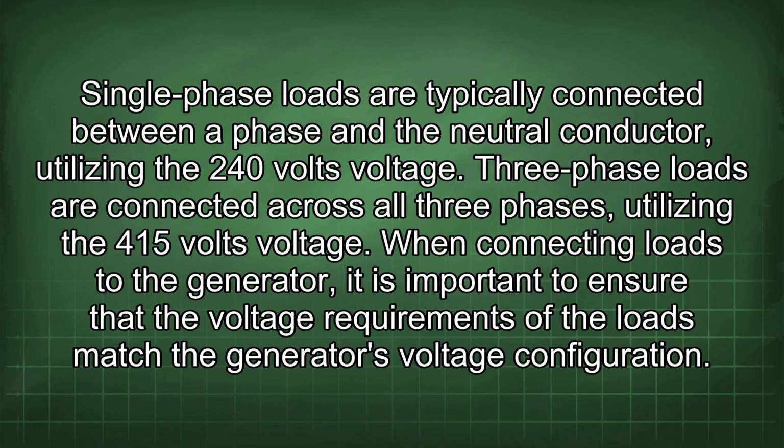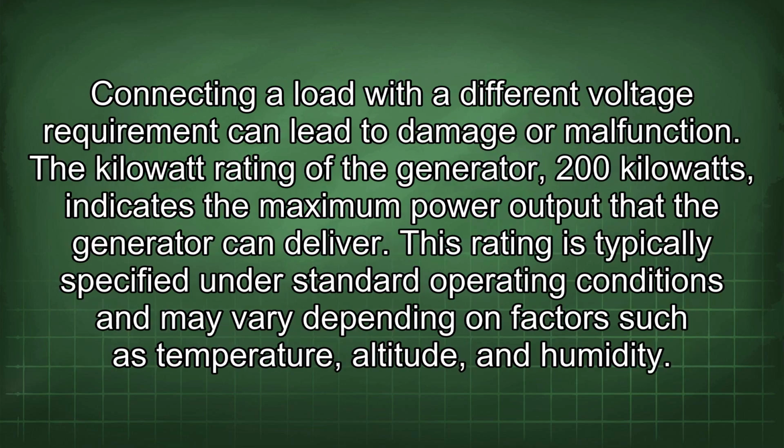When connecting loads to the generator, it is important to ensure that the voltage requirements of the loads match the generator's voltage configuration. Connecting a load with a different voltage requirement can lead to damage or malfunction.